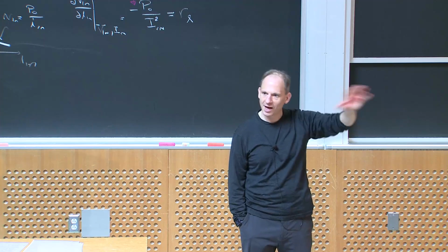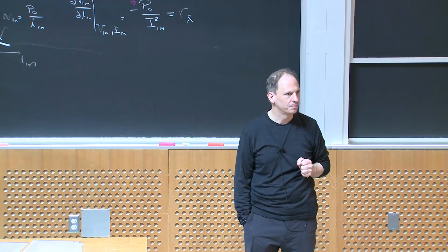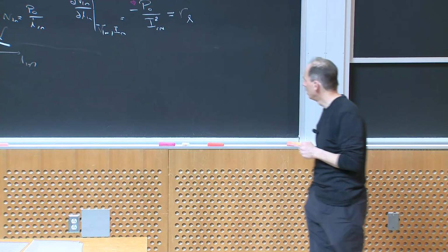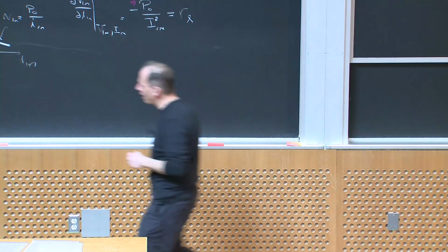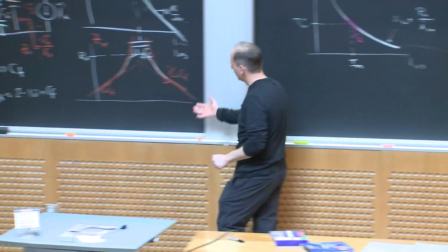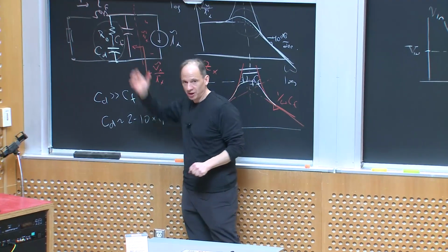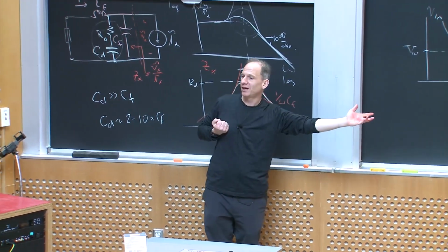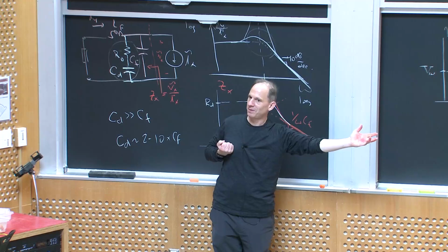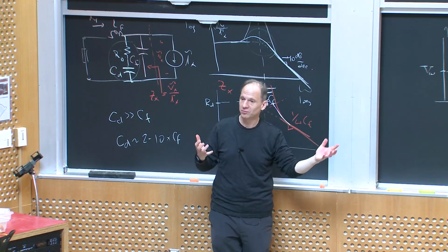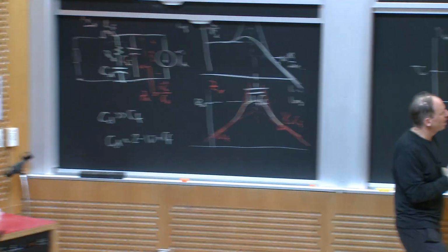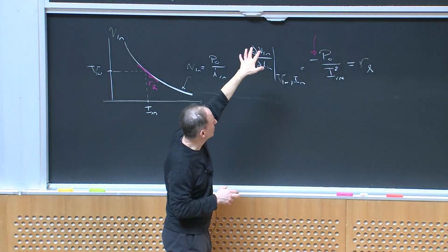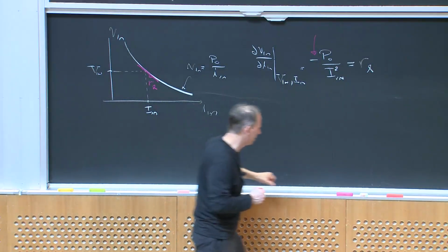You can start to make oscillations in constant power loads. Generally, the reason we obsess over the output impedance of our filter is because I need to keep it small enough that when it looks into a negative input impedance, effectively a power converter, the whole system's going to be stable.